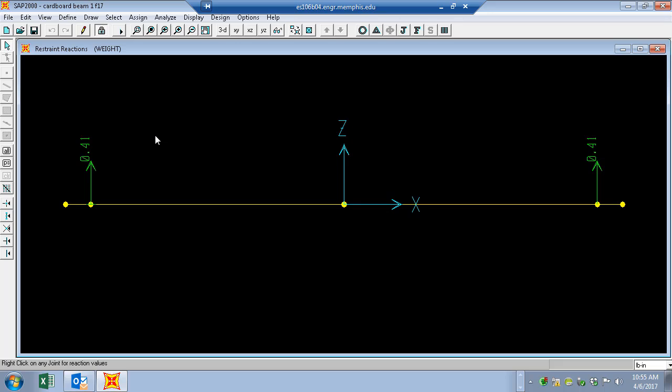So if you want to get this displacement down, what are you going to have to do? Do you need to make the beam wider or taller? Probably taller. So you could double the height of the beam, still be in the rules, probably only double the weight. What do you think the displacement would go to? Well, that's something for you to explore. Okay? So any questions about that? I'll just get you through the first part.